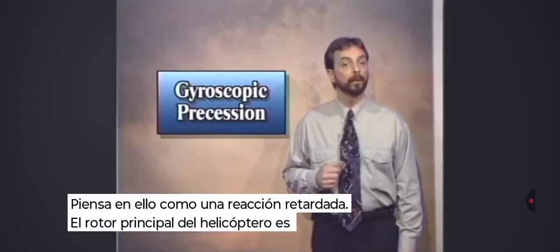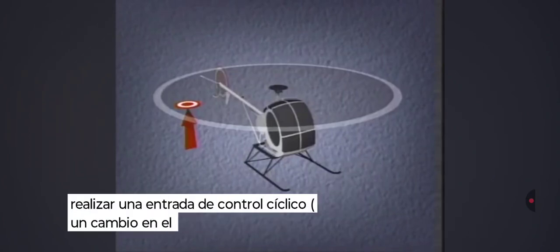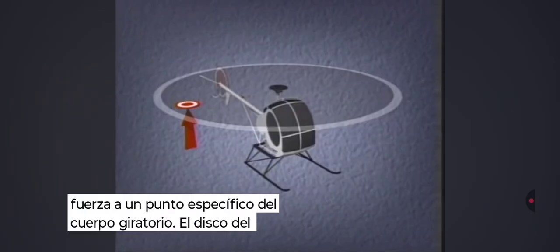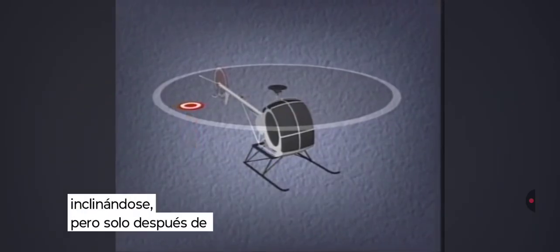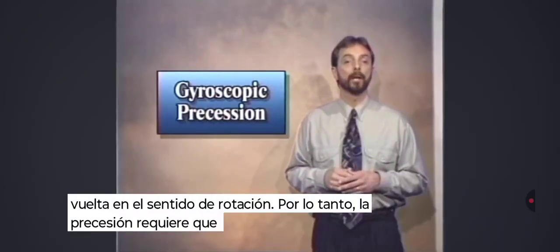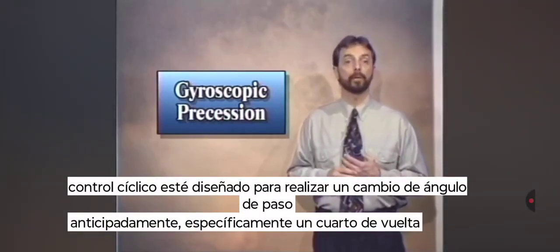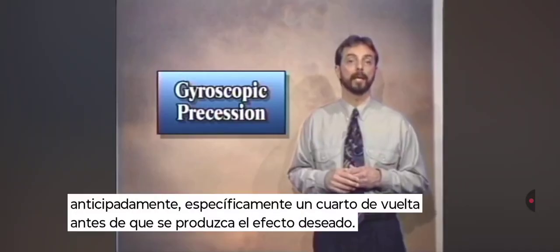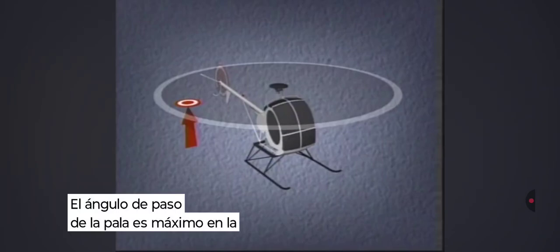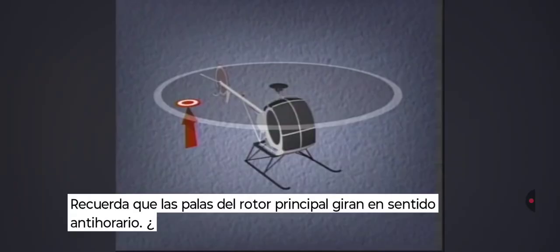Well, the helicopter's main rotor is a rotating body, just like a gyroscope. When you make a cyclic control input, which is a blade pitch change, you're applying a force to a specific point on that rotating body. The rotor disc will react by tilting, but only after making another quarter turn in the direction of rotation. So precession requires that the cyclic control be designed to make a pitch change early, specifically a quarter turn before the desired effect needs to take place. The pitch angle of the blade is at a maximum at the 3 o'clock position, which is on the pilot's right. Remember, the main rotor blades turn counterclockwise.